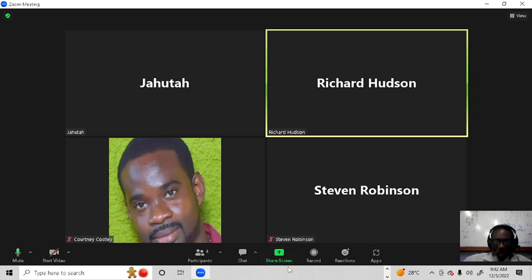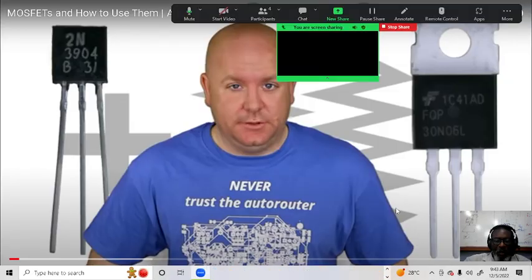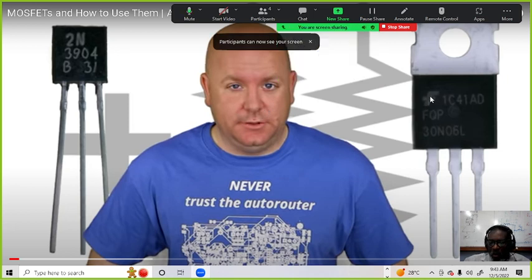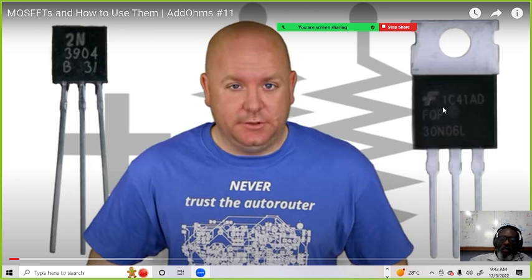But if I show you some other transistors, how do you know the difference between a MOSFET and a JFET? Most of the time, you'd have to use the number that is on the transistor itself, right? But sometimes I use this little funny looking writing here, this little F, to know that it is a FET. Most of the time, you see the F on the transistor, because you have BJTs that look just like this as well. Alright?